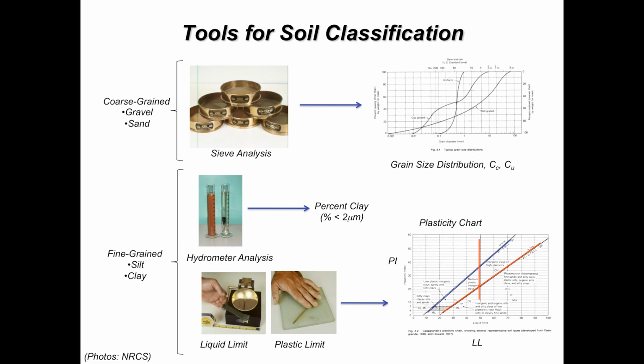So again, we see these what are certainly very archaic methods that we use to classify clays that are really only indirectly linked to the things that are actually controlling whether or not that clay is plastic, or whether or not it absorbs water. Those things are mineralogy, surface area, cation exchange capacity, and so our intent here is to get a little bit closer to those fundamental clay properties.